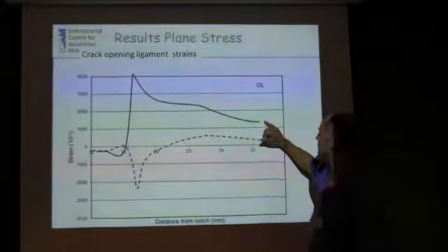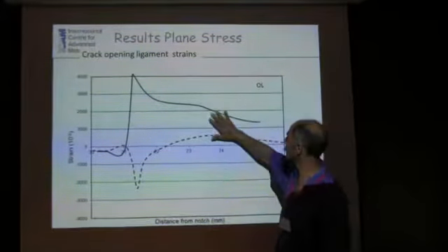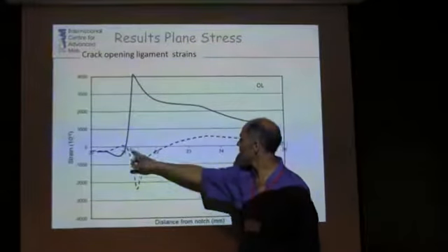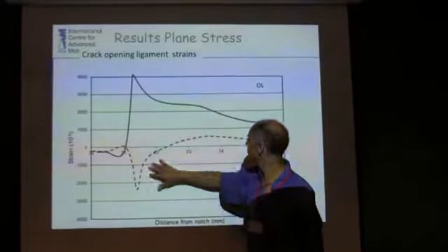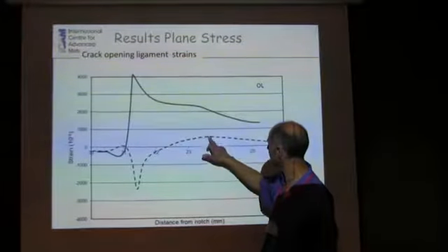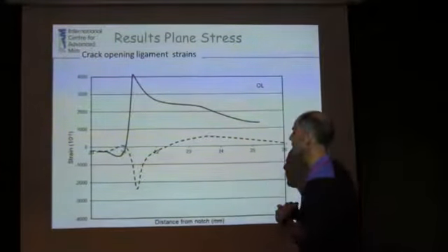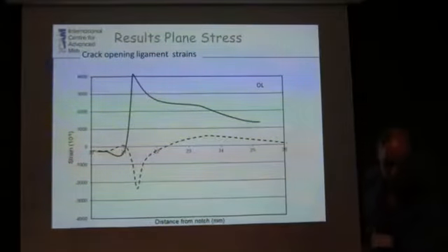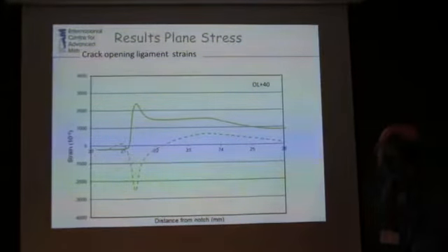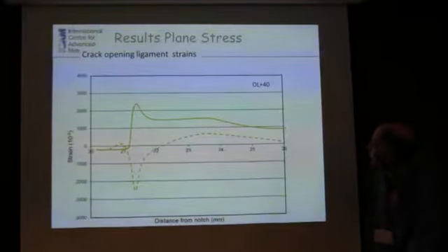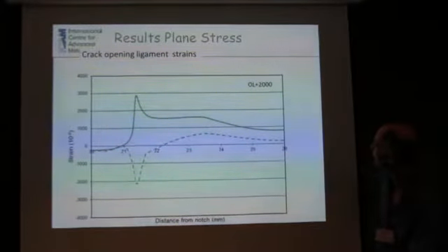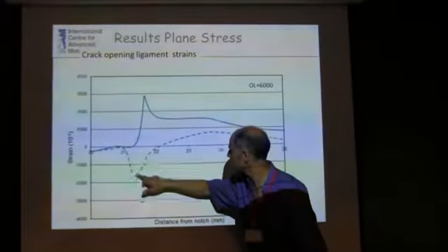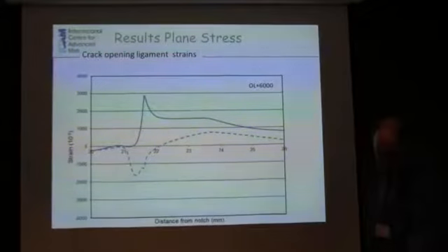What we notice is we start to get a slightly different field. You get a much larger area here. It goes flatter here. This peak is now much larger than before, and the peak's tensile stress is actually 2.5 millimeters ahead of the crack, and we get this definite shoulder. And you can see again, as we go a little bit further beyond the crack, we're starting to get a double peak here as we grow the crack.